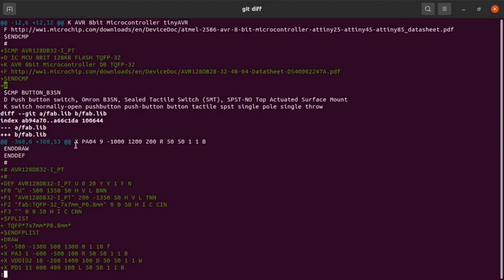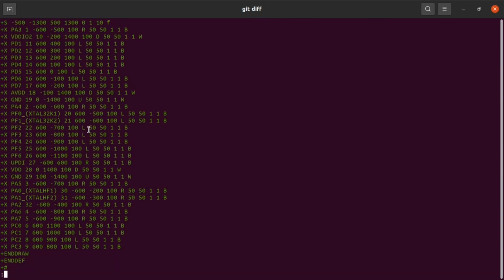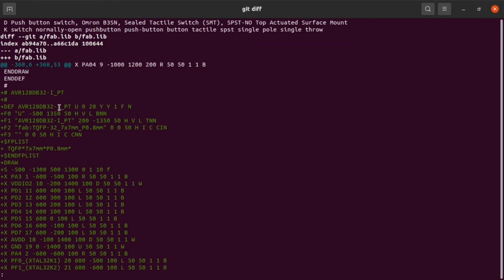And then in the lib file, we have the actual component entry. So there's a name, then there's the definition of it, which also shows up in the editor. There's what kind of designator it should have. I think this is a location where it should be.